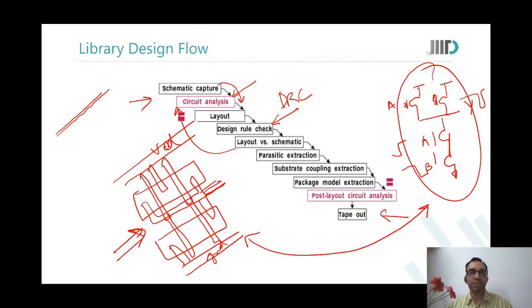This you noticed even in the chip implementation flow last time, where we said that once we have the post layout stuff, we go back to the STA stage and see that even after the post layout, things are still fine. You remember that? So we do lots of to and fro runs to ensure that things are as they were expected to be. And this layout versus schematic is one such back and forth run. Is that okay? Any questions?